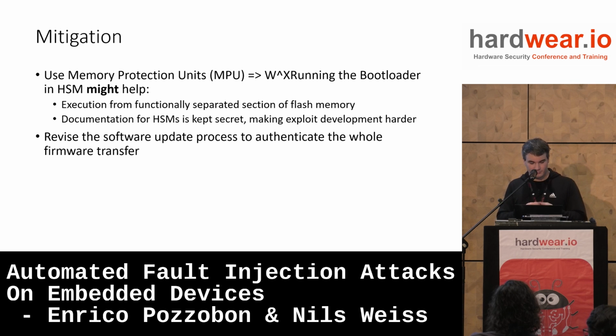Or you just revise the update process to authenticate the whole firmware transfer, because the problem here was that we were able to control a large part of the flash. So a Boolean flag that tells you whether you can execute it or not is not enough. You need to authenticate every single write. So something like TLS should work here.